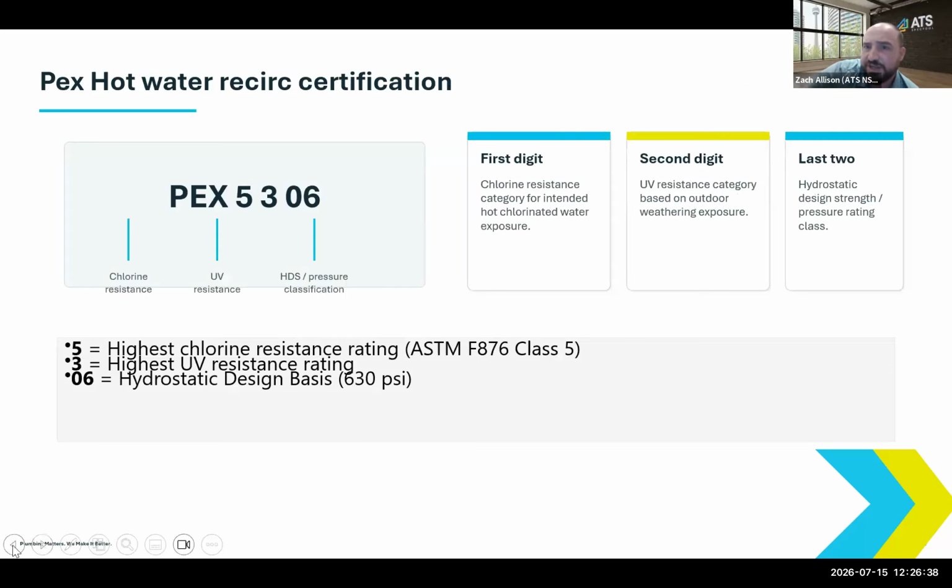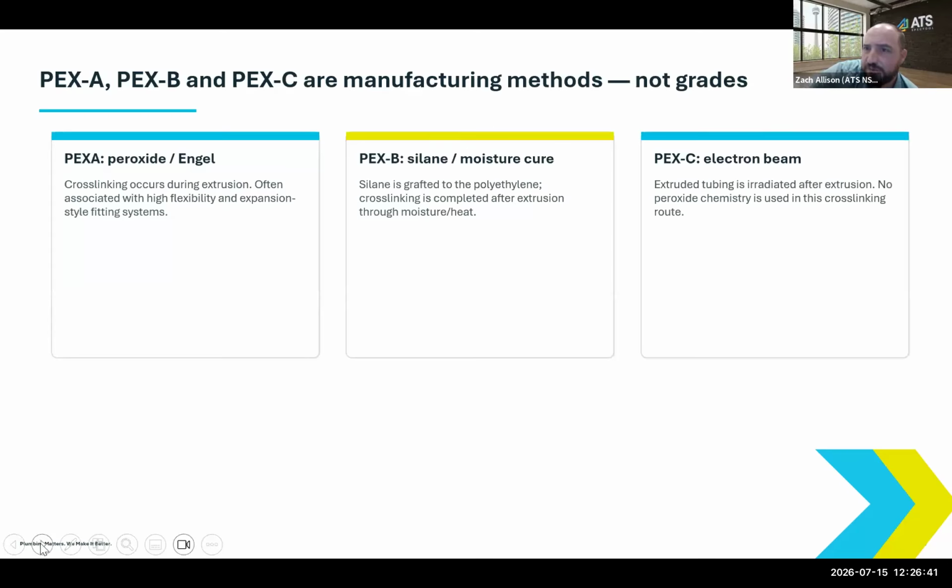And last question, is PEX-A approved in Ontario for ceiling plenum application in terms of smoke and flame ratings? I think you probably get to those smoke and flame ratings later. Yes, we can wait for that if you want. Not every manufacturer is approved. So before you specify something, you're going to have to go to their website and download